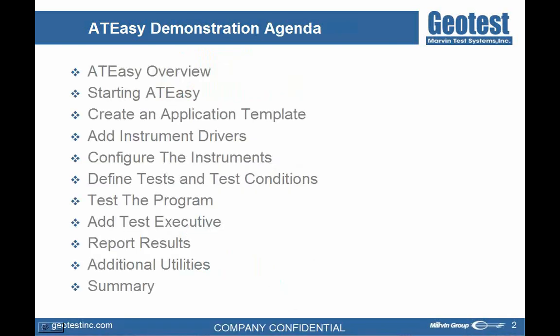Let me start first off with an overview of what we're going to be doing today. So the agenda for this morning is we're going to just do a short overview of ATEasy, what ATEasy is. I'll give a demonstration of how to start ATEasy as an application on your system. We will create an application template, which is basically a blank application. We will then go through the process of building an actual application, starting by adding instrument drivers, configuring the instruments for operation, defining tests and the test conditions.